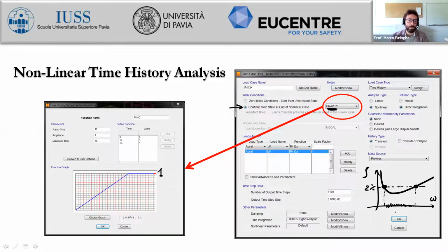In these cases, an exception is made for rubber bearings. For the other two typologies, we have nonlinear behaviors. But in any case, we can consider a very wide range of angular frequencies, so that at least a maximum value of 2% will be considered. But it could also be lower, because this is the behavior of the Rayleigh formulation.